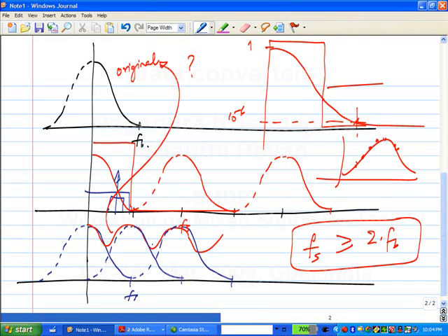No, but yeah, why do we assume it's white? It is certainly correlated with signal, right? Because for every sample there is a certain quantization error. It is very much correlated with the signal. Why do we get that white-like spectrum? Yeah, that's true. The result you are getting at is right. But how do we even get it? Because we know that it is certainly correlated with the signal. Because if I round off 75 paise to 1 rupee, I know that the error is 25 paise. There is no other thing.